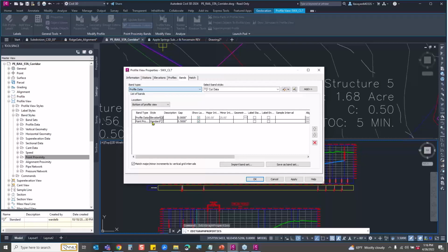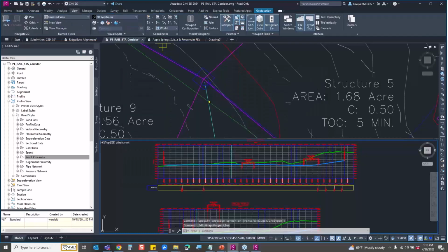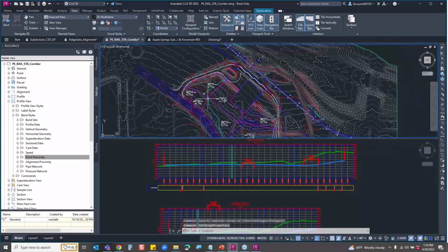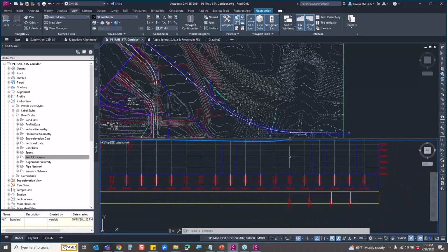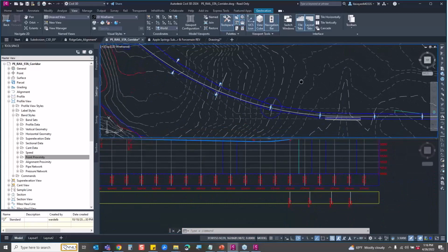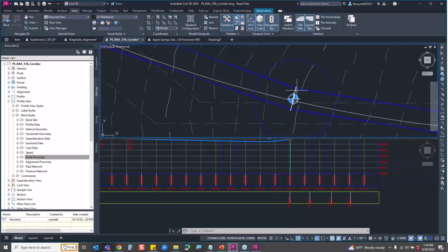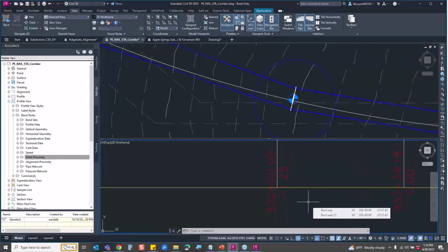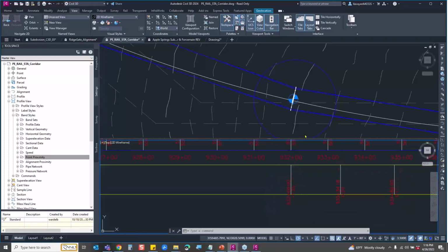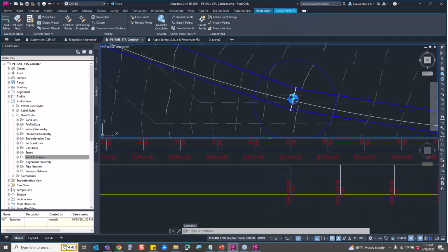So as I start looking at something like this, I could take a peek at, what am I looking at here? Okay, what is the station? Around station 9300, right around here, I can see that I have a point, and the point that I'm showing off here, as what looks like a benchmark, is being lit up, and it starts at station 932.2, and it's about 1.5 feet away from the center line. So it can mark points that are around that particular alignment.